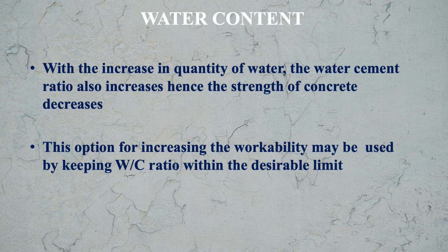So as you know that strength of concrete depends upon water cement ratio. So if you are increasing the quantity of water, then water cement ratio increases, and as you know that with increase in water cement ratio, strength of concrete decreases. So that way quantity of water should not be beyond a certain limit. This option for increasing the workability, which means increasing the water content, may be used by keeping water cement ratio within the desirable limit.